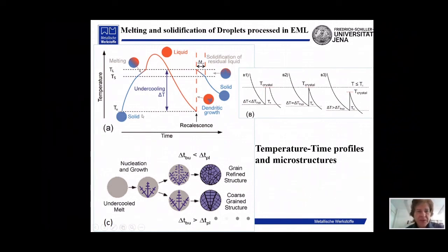So, for instance, this period is several minutes or half an hour, takes several tens of minutes, and this period, I told you, primary solidification, the duration of this primary solidification is about 10 to the minus 4, 10 to the minus 3 seconds. Because of this, the slope is not visible here. But there is a period from recalescence to coming to this point, slightly below liquidus. In the scheme, we showed that this is the liquidus temperature.